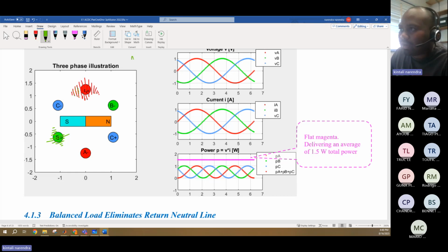If the total number of windings is Ns, then Ns by 2 sine theta is the number of windings at a given point of time. Here, if you imagine it is 10 degrees, then Ns by 2 sine of 10, sine of 20, sine of 30. When sine 90 comes, you have maximum windings at the center.